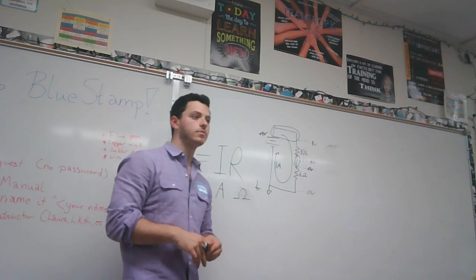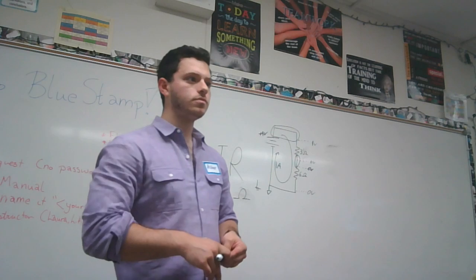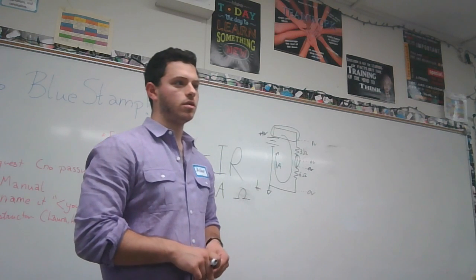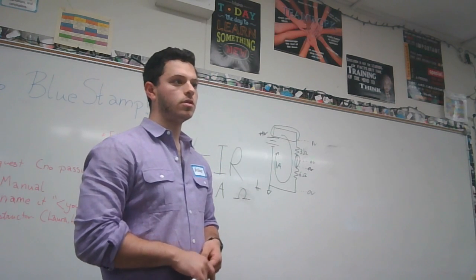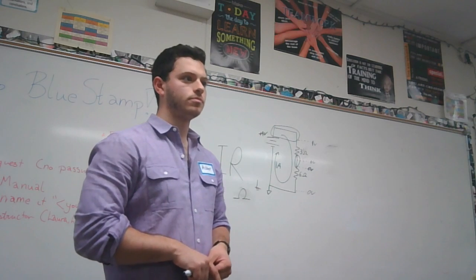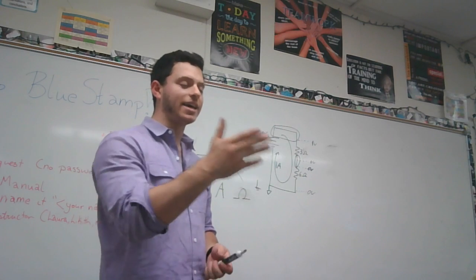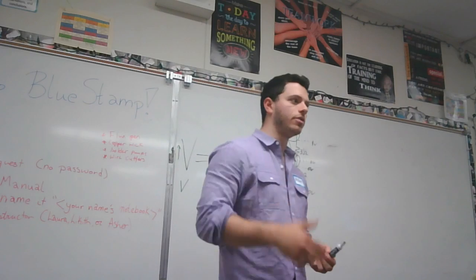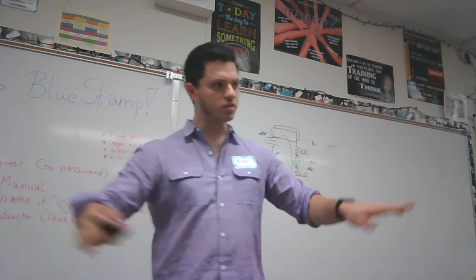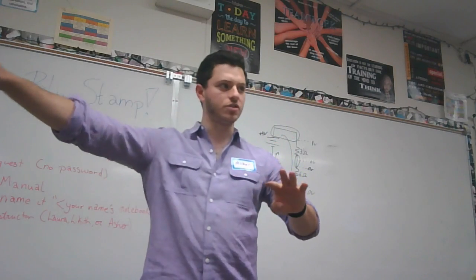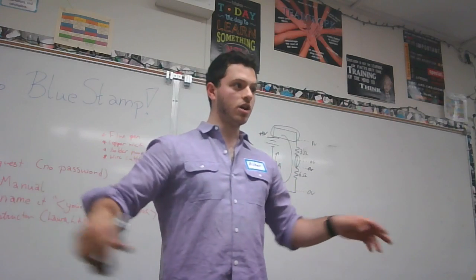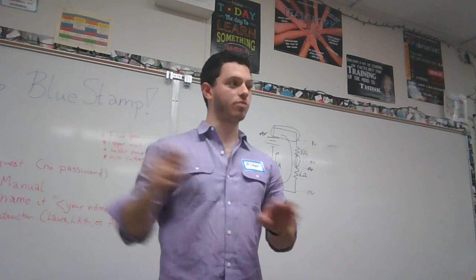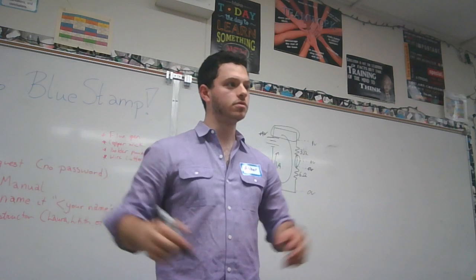Yeah. So when you use the ground, like on the breadboard, is that like you're defining that as 0, or like you're finding the value of that? So in that case, you are personally defining it as 0. You're saying this is my 0. This is where I'm going to tell every other part of my circuit this is where my ground level is. Whatever your voltage is now going to be in reference to this being my ground. Okay.